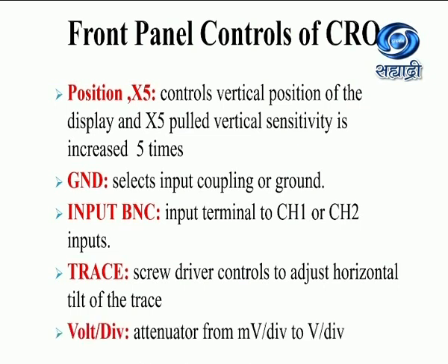Then we have volt per division. Basically this is internally connected to the vertical attenuator, and you can adjust the amplitude of the signal by using this control. The attenuator ranges from millivolt per division to volt per division.